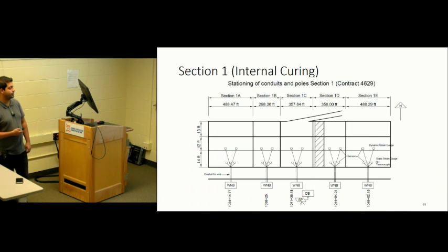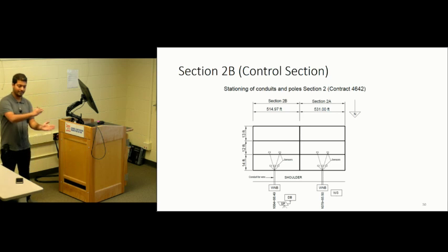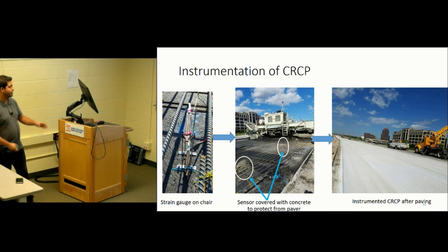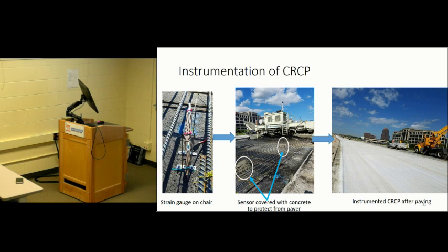What we usually do is, if we don't embed it, it overturns because of the movement of the concrete flowing through the slip form paver. So they put the fresh concrete from this side of the slip form paver, and the concrete gets distributed and leveled by the machine over there.